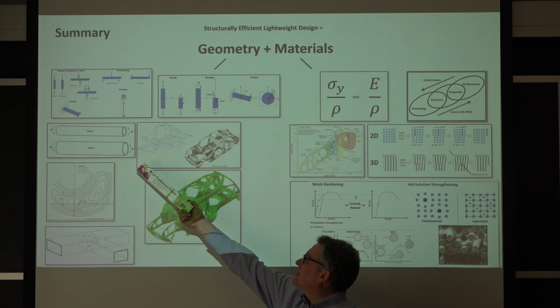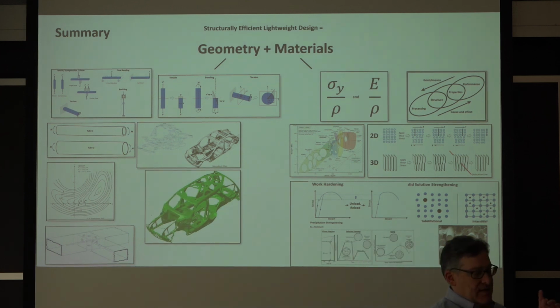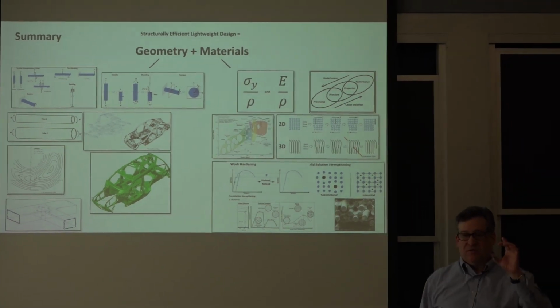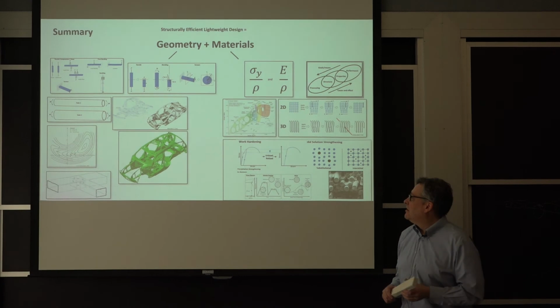And we talked about this idea of going from a tube that has a small diameter with a thicker wall to a tube that has a bigger diameter with a thinner wall, which in net can produce a tube that's stiffer in bending or torsion than we could if the material was smaller in diameter.